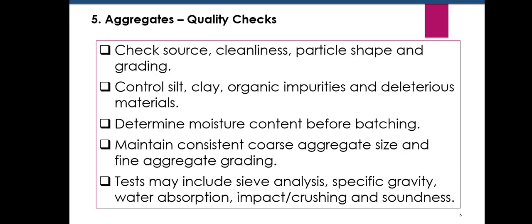So, next is about aggregates. Aggregates occupy a major portion of concrete volume, so their quality has a major influence on concrete performance. We should check their source, cleanliness, particle shape, and grading. Silt, clay, organic impurities, and other deleterious materials must be controlled.